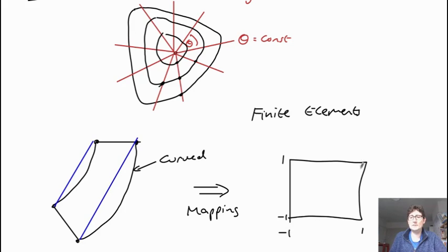So we have a standard size square in some normalized coordinates r and s. So s is this distance around here, and r is this over here. And so we normalize this. So this might be some function of r, and this might be a function, say alpha of s. So there's a mapping from this real space onto a normalized space of r and s.